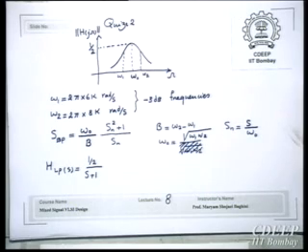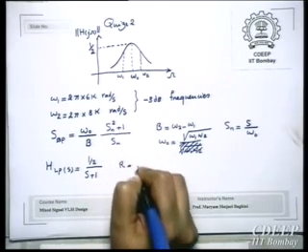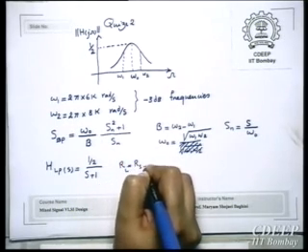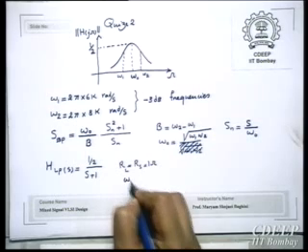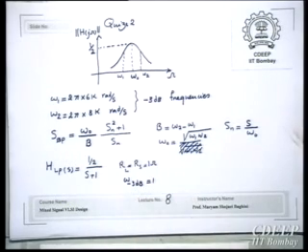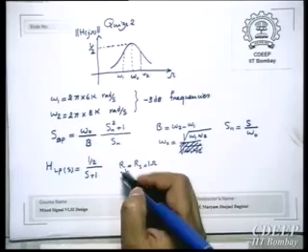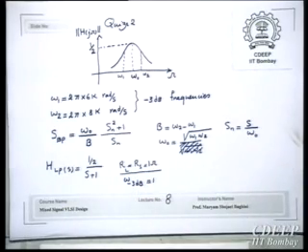It is S because it is effectively normalized. Means that this is for R equal to RL equal to RS equal to 1 ohm, and omega at minus 3 dB also is 1. So it's normalized. For band pass also you consider RL equal to RS equal to 1. So it's just frequency. Realize the filter using LC.